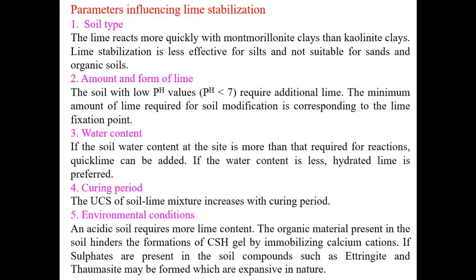Further, the pH of the soil system also reduces, which constrains the development of pozzolanic products. With the increase in temperature, the pozzolanic reactions increase, solubility of calcium hydroxide decreases, but solubility of silicon dioxide increases.